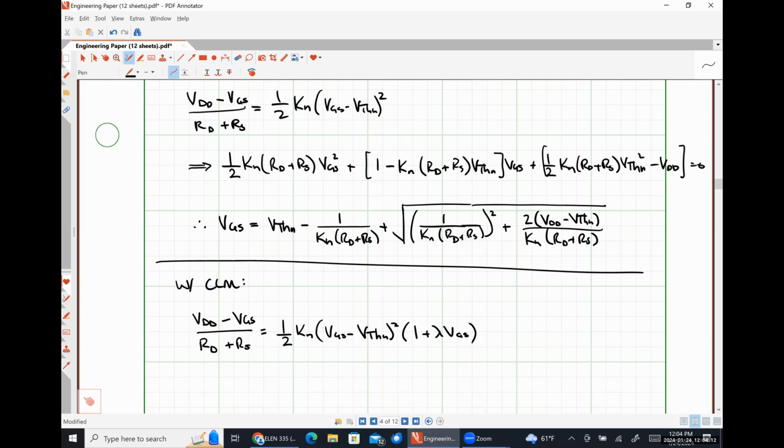So that's DC biasing of NMOS circuits, right? So we have literally just two different circuits to worry about. The 4 resistor biasing network, which we can modify to look like any of the other networks, like simple biasing, resistor divider biasing, etc. And then we have our self biasing.